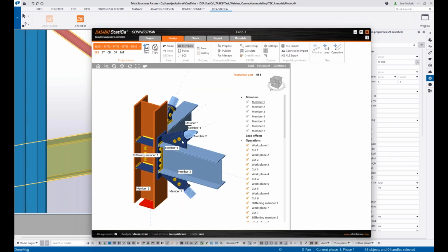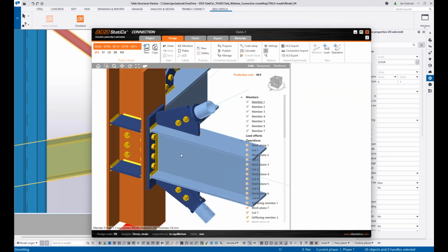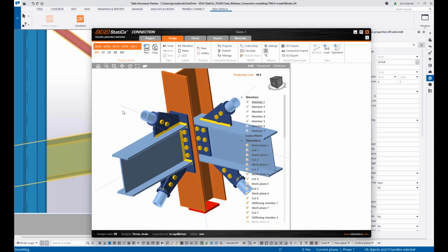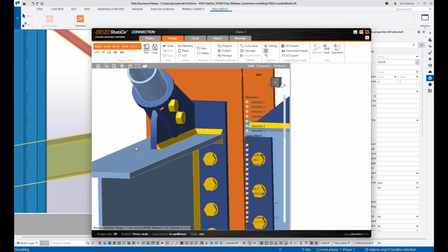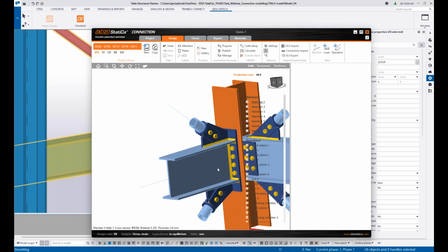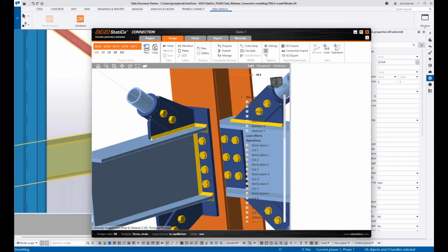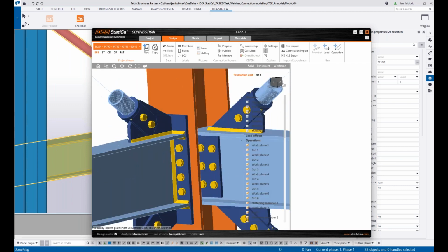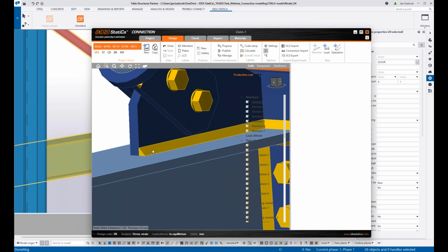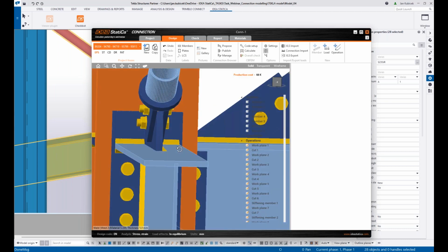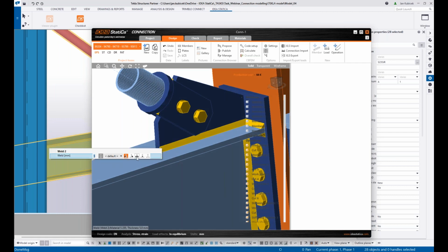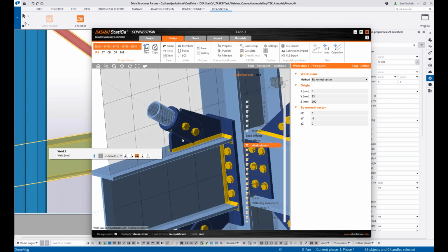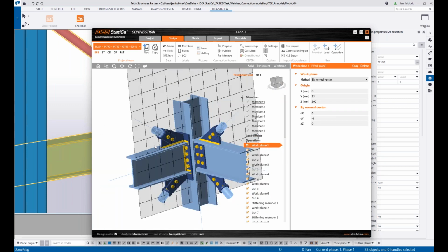Still working. Okay, it's here. Perfect. So what we can see here, it's the same connection, and we could just simply load it and calculate again. And from these CAD applications, for example, Advanced Steel, Revit, or StatiCa structures, sometimes some information could be missing. Some information as a weld type can be different from what we expected. So very simply, we can fix it in our connection model, and it would be correct very quickly.